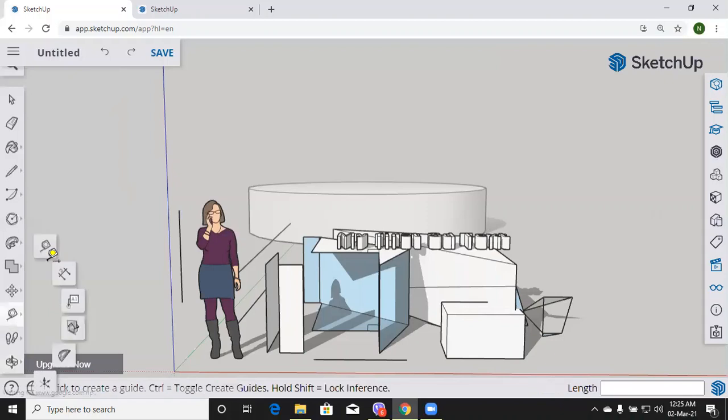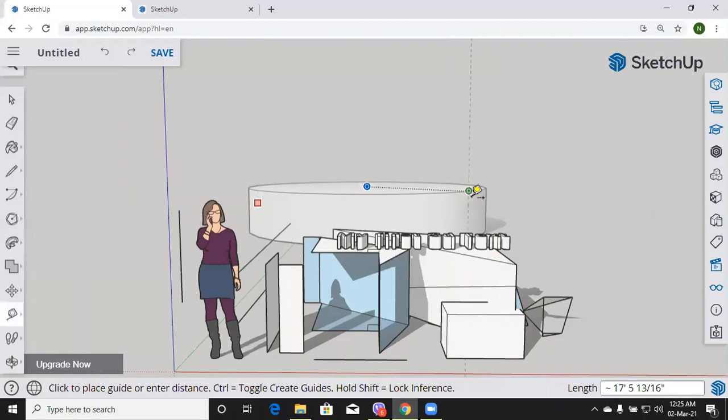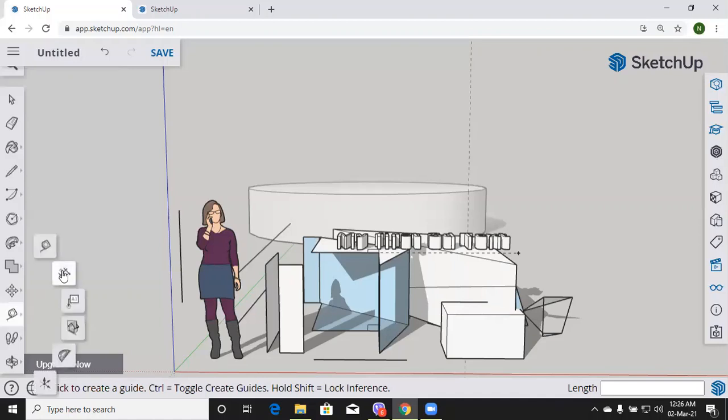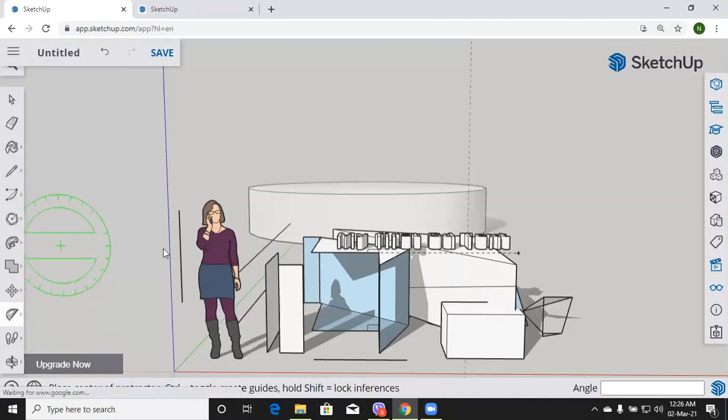Take measure. You can measure however you want to measure it. Everything is given here. Look here, you can measure it like this. And then you can even set the annotation styles also. You have different dimensions, and then you have text also, and you have section plane also. You can just set the annotation styles also. Precision in the model info panel also you can set.